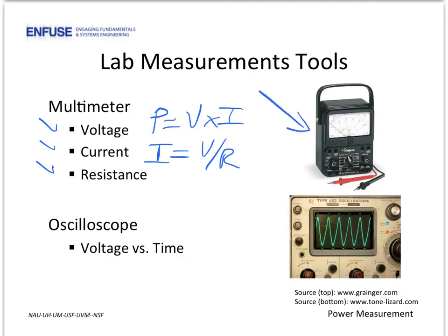Critically, for power systems, one needs to understand the phase relationship between voltage and current. Ideally, these two are in phase and therefore power is being delivered most efficiently to the resistive loads. However, real loads are complex as they have unwanted inductance and/or capacitance. Also through Ohm's law, a complex load results in voltage and current not being in phase, thereby reducing instantaneous and average delivered power. We can use an oscilloscope, such as this unit here on the right, to look at these waveforms as a function of time to understand their phase relationships.